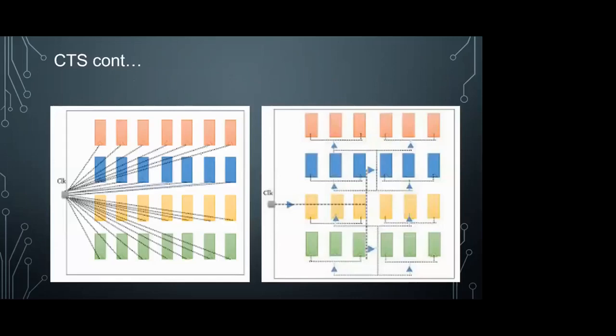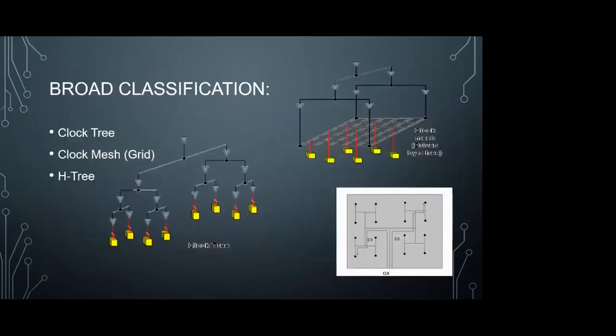So inside the design you can see like this. Okay, these are the flops. So before CTS it will be like this. So after CTS you can see buffers were inserted, right? So to minimize the skew and insertion delay.